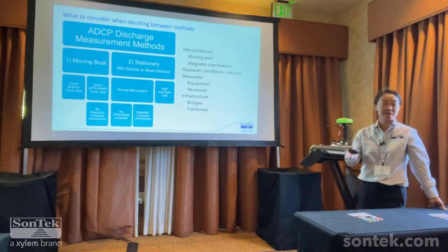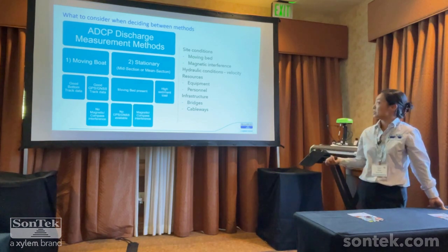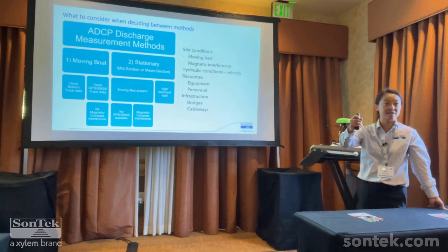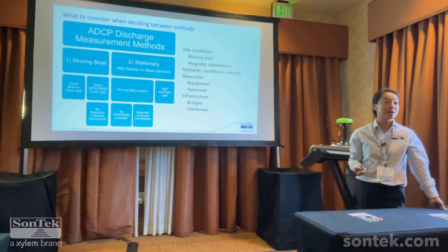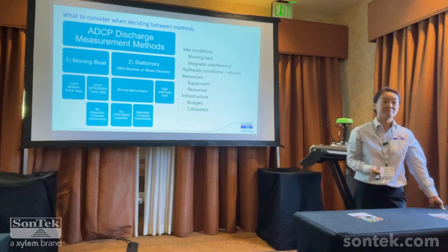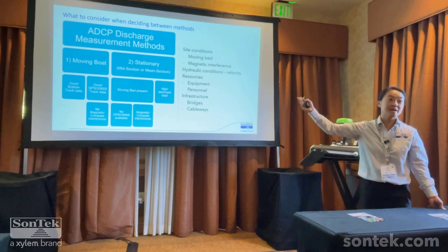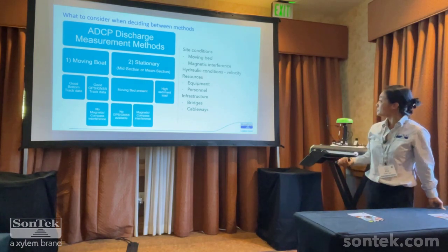Stationary, because you know the location that you're at with the boat, you can get around the moving bed situation. Oftentimes a high sediment load helps you stationary because you're sitting there measuring and pinging continuously at the same location. In that way you have a higher probability of getting good ensembles compared to the moving boat method where you just zip through at any given point.